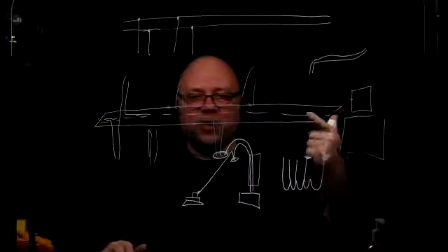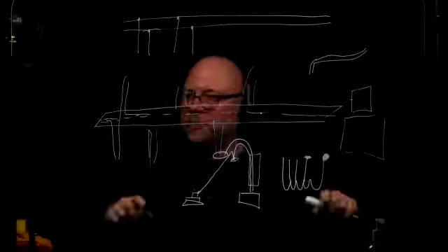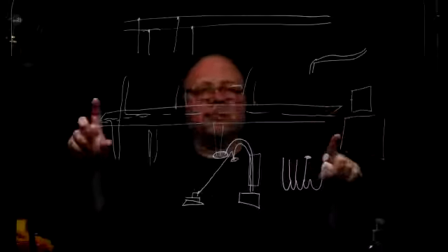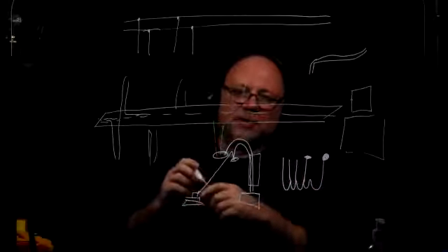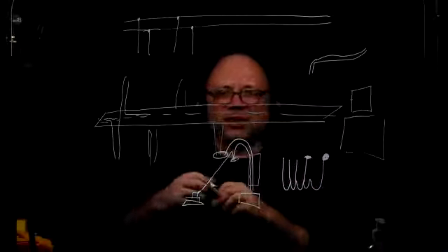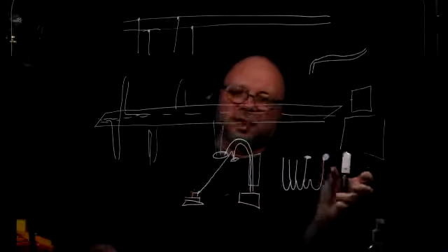Bigger, smaller, or exactly the same? Match it. Right? Without going for too long, I'm going to say match the power. There's a temptation to say bigger, but not necessarily. With a bigger amplifier, if you're not careful, you're going to damage the speaker.